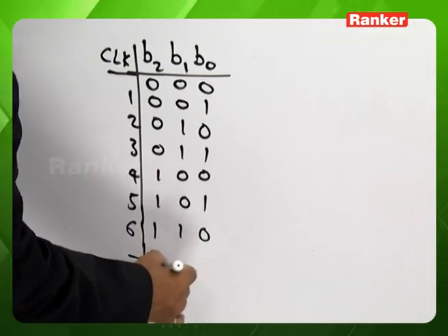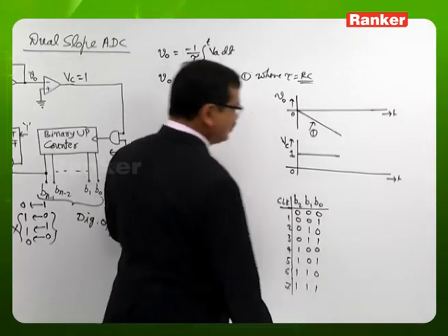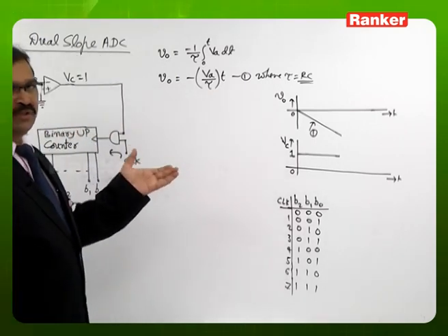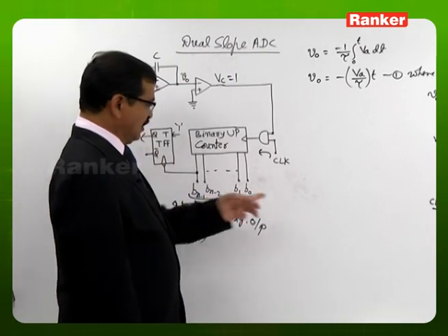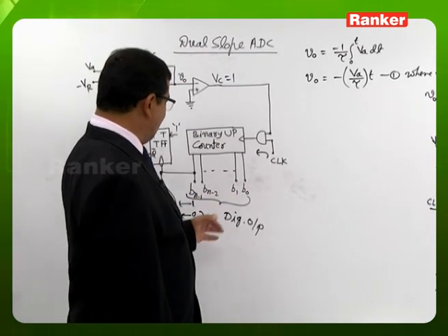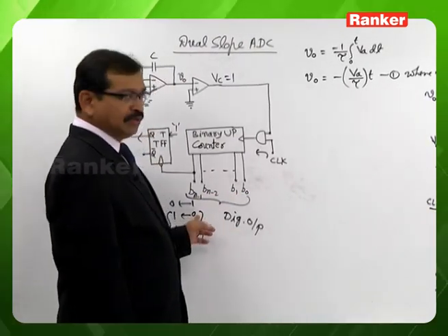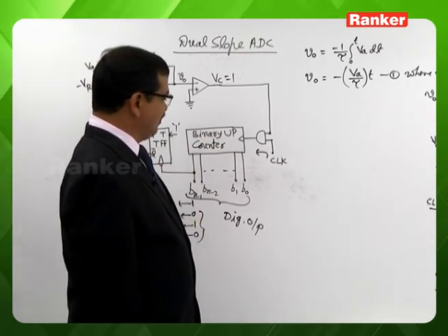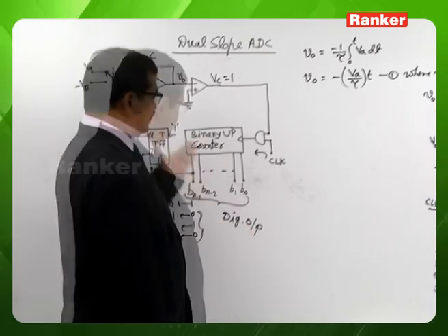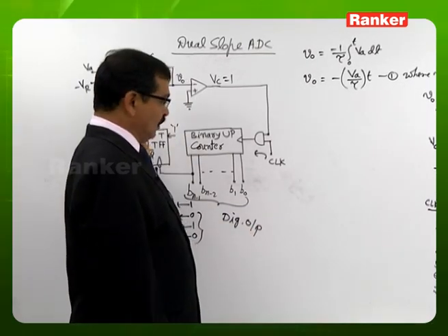Even until the 7th clock pulse, for this 3-bit case, the MSB bit B2 does not have a chance to change from 1 to 0. Until the 7th clock pulse, the change on B2 is either 0 to 0, 0 to 1, or 1 to 1. Hence, the T flip-flop was not able to toggle till now.